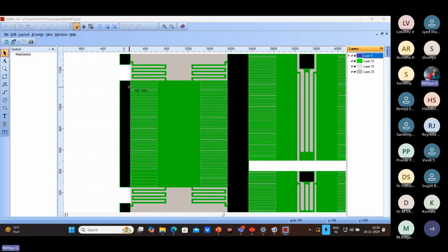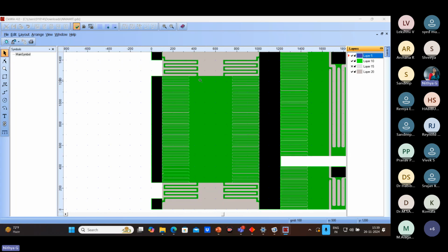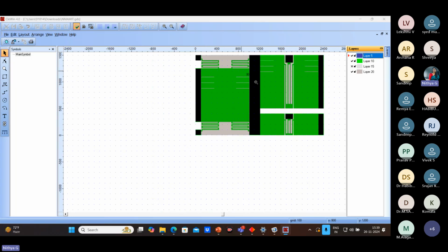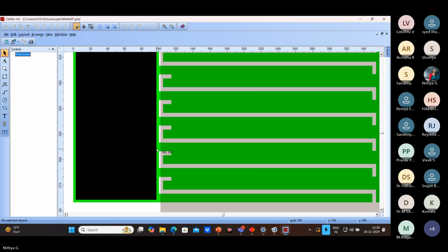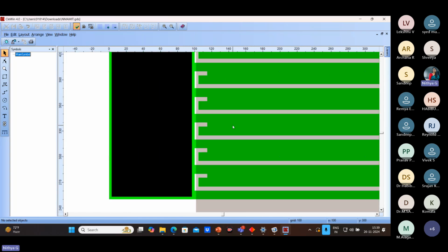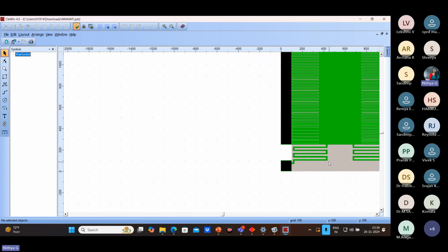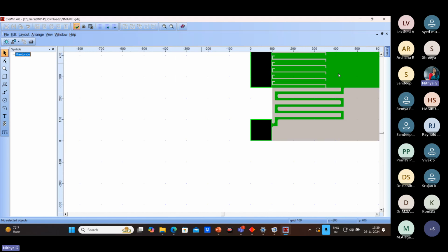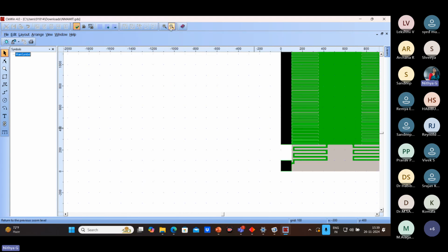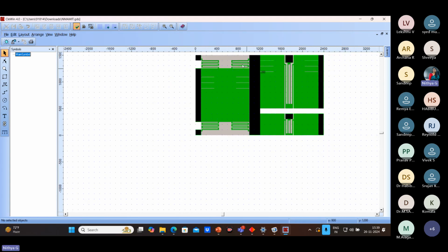Only at these places I need to remove the areas. The spring should be made free. The proof mass should be made free. That is why I create a trench, so that during fabrication the mask layer related to the trench defines that under this area I need to remove the substrate layer.